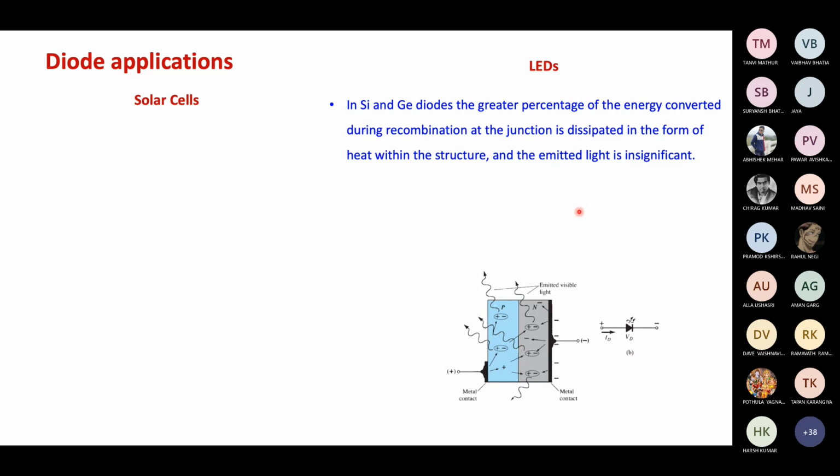And this is a good question, I would say, because the design of a simple diode and an LED diode is actually different. The doping amount is different because in LEDs, typically we need to have high recombination, so we need to have high doping, and we can even have graded doping if we need recombination in a certain region. But let's not go into the graded junctions at the moment.